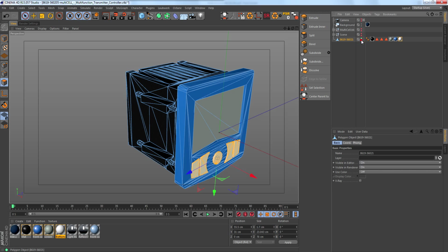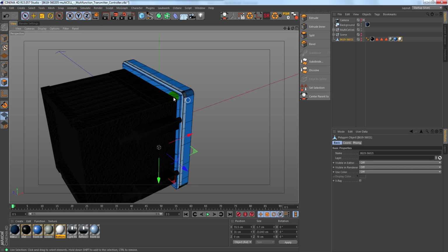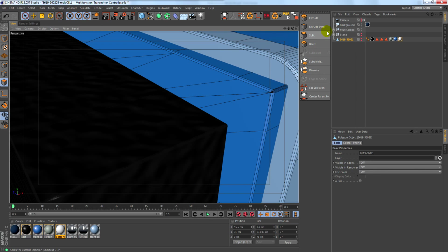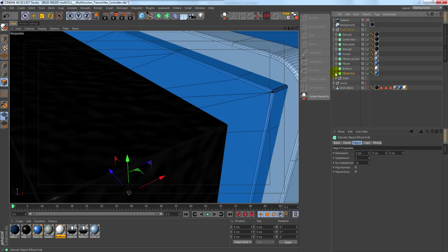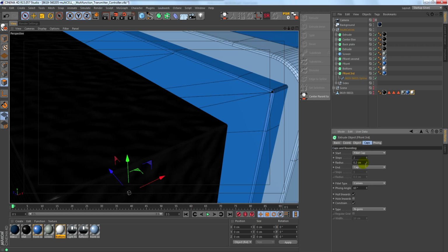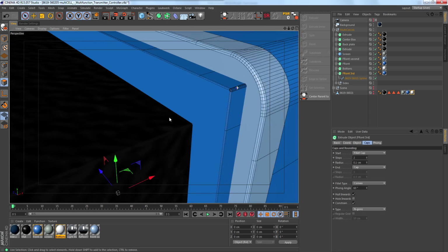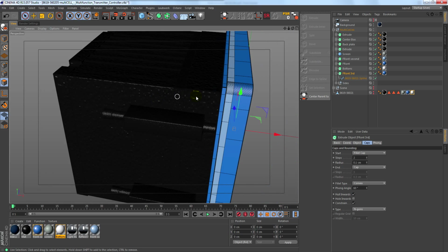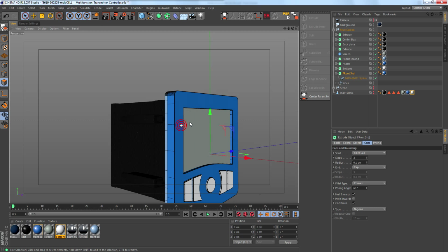And then if we have a quick look at my version, you see we've got very clean lines, apart from these lines here. We can just come in here and change this. Come over to the third one here, do the caps, put them to 0.1. That fixes that problem. We've probably got too many points there, but as I'm going through, I'll show you how to optimize this and take you through every step.